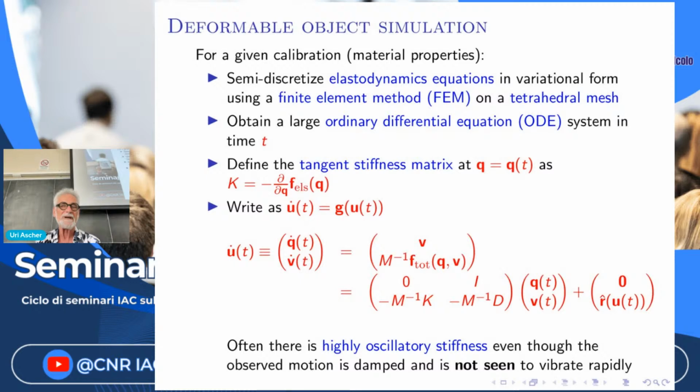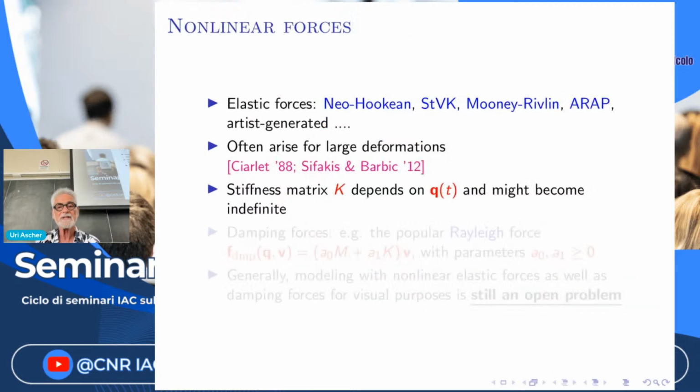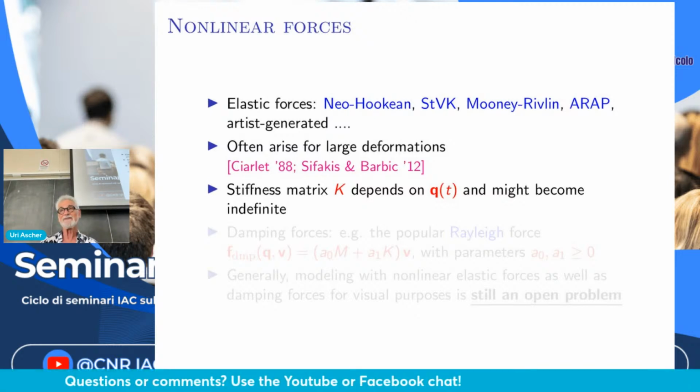Okay, so we have a stiff problem. We must use an implicit method, not explicit, for discretizing this. And just to add misery, the forces are nonlinear, because Hooke's law, which is a linear force, doesn't generate interesting animations. It's kind of lethargic. So you want nonlinear, non-Hookean, neo-Hookean, or others. There have been many proposed by applied mathematicians. This is something that only computer graphics people understand, and so on. Many different options have been looked at.